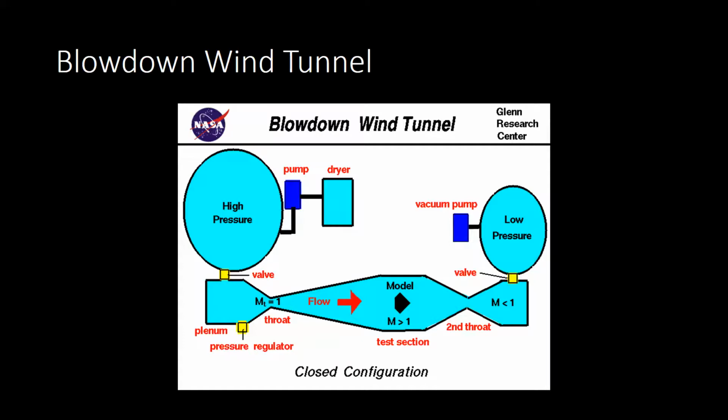Essentially, in Bernoulli's, you're used to increasing cross-sectional area reducing the velocity. But in supersonic flows, you see the opposite. This is caused by the temperature, pressure, and density building up right here. As you expand this, the temperature, density, and pressure are all reducing very quickly. This can have some negative side effects, like the air can actually liquefy. And obviously that won't be very accurate for the simulation.